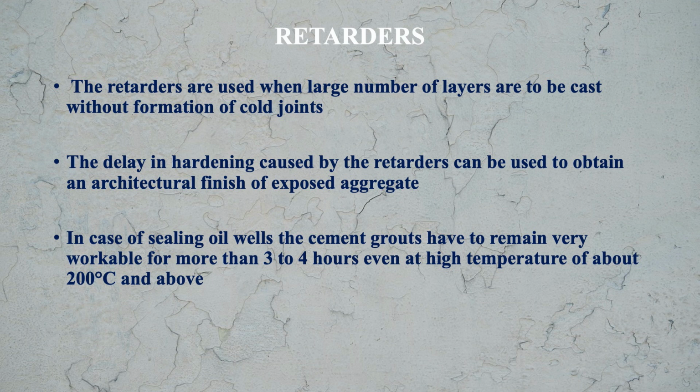You have enough time to do that. In case of sealing oil wells, the cement grouts have to remain very workable for more than 3 to 4 hours, even at a high temperature of about 200 centigrade and above. So this admixture helps us in keeping the concrete workable for a longer time.